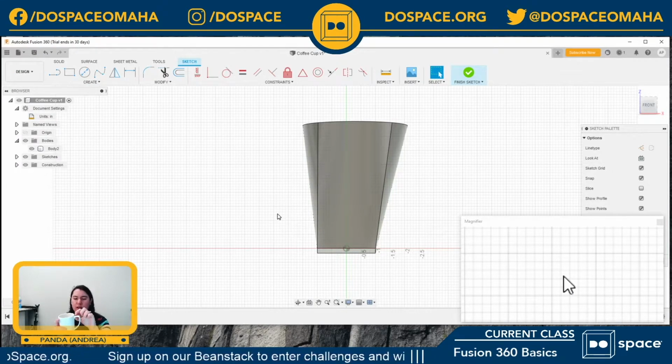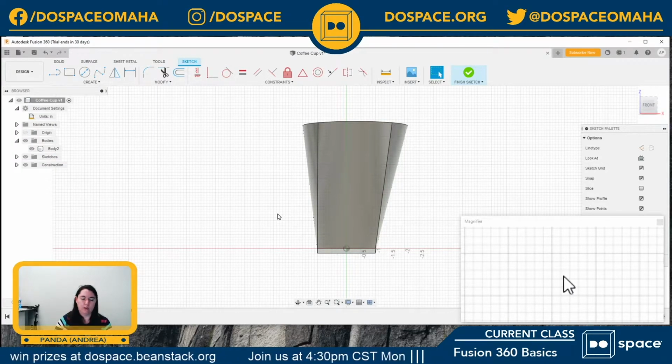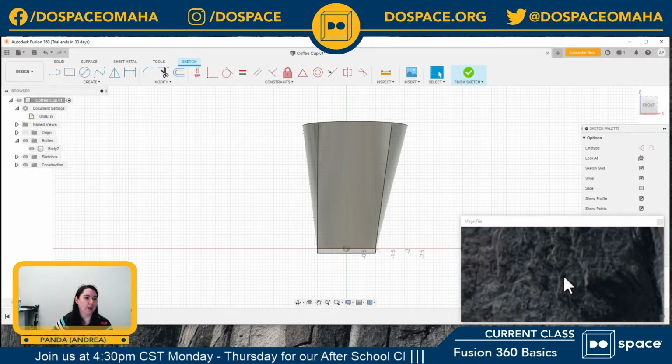And then with that little oval profile, I'm going to create a line that goes right in the middle of my handle, and I'll rotate this circle around the line to make that half donut, and that's what our handle is going to be made out of. And so the first step, we're going to create a shape that's going to match kind of like a cut. If you were to cut this, what that would look like in profile for our handle.